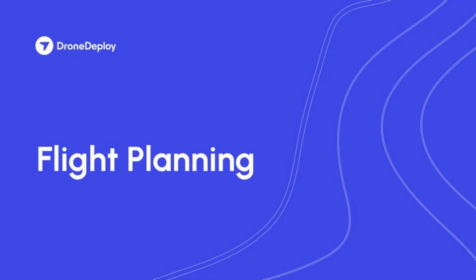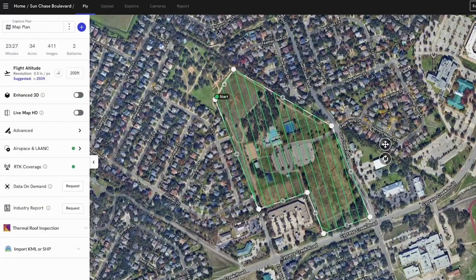All right, we're going to first talk about planning your flight before ever going out to the field for your high accuracy mission. So the first thing we're going to do is a standard map here. Now, considering that we chose a single GCP workflow, it was based on a few factors. The first one being the number of acres here. This is a relatively small site, so we can get away with choosing a single GCP workflow here. And our accuracy threshold for this isn't super high, but you'll see we'll still be able to achieve sub-inch accuracy on this map, flying the Mavic 3 Enterprise with RTK and with that single GCP.